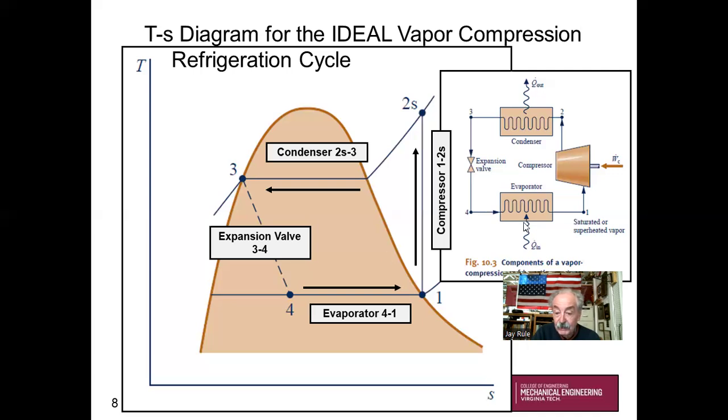So that way you can absorb heat from the cold space into your evaporator, process 4 to 1. So we're starting at a saturated mixture. We're adding heat to that. We're not lifting a weight, no shaft coming out, but at constant pressure we're adding energy until we reach a saturated vapor phase. Look, it's still kind of cold. It's constant temperature. It's still cold, but now it's going in the compressor to repeat the cycle.